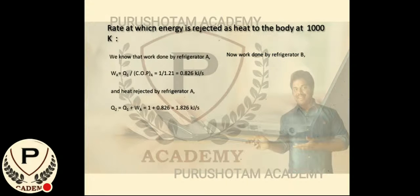So now work done by refrigerator capital B. So WB equal to Q3 by COP of B, that equal to 1.826 divided by 1.21. So you may ask how we are substituting the value of Q2 in Q3. As Q2 equal to Q3, we can substitute the value of Q2 in Q3. Okay, so since Q3 equal to Q2, we got 1.826 divided by 1.21, that equal to 1.51 kilojoule per second.